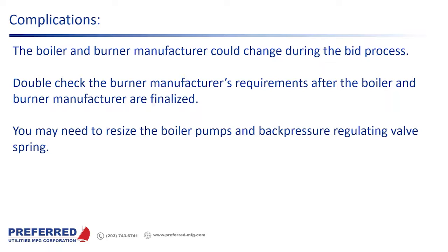So after the boilers are awarded, the plumbing engineer needs to go back and get the submittal on the boilers and the burners and make sure that if you designed around steam or air atomization, that pressure atomized burners didn't sneak in. Because if it's going to be pressure atomized burners, then your oil pumps are probably going to need to get bigger, and your back pressure regulating valve is going to need to change to one with a lower spring range.